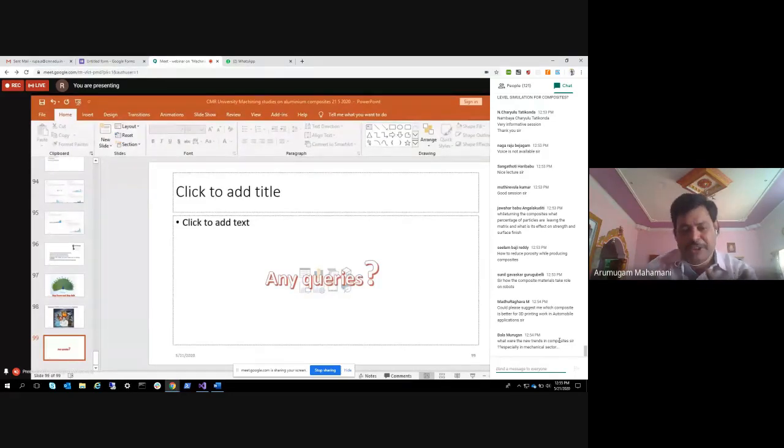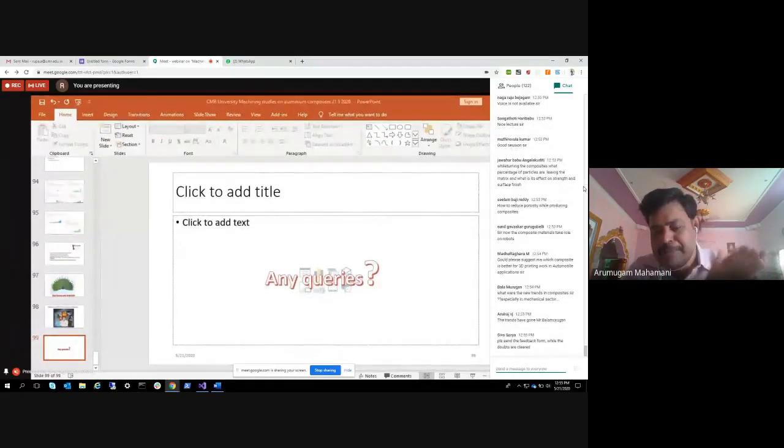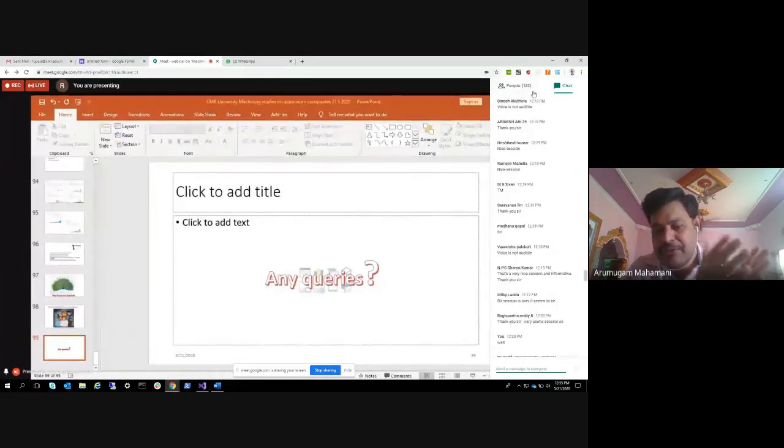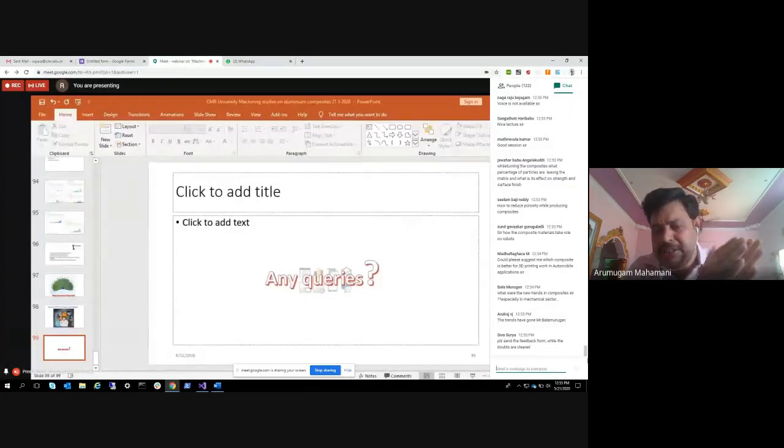So my composite property is very good, but I cannot keep it for the exhibition. It needs to go for application. More fiber content will restrict the applications. Normally people go up to 40. More than 40 limits the application. Simply developing mechanical property, everything is good. It is one way of research. But for real-time application, low fiber content is required.